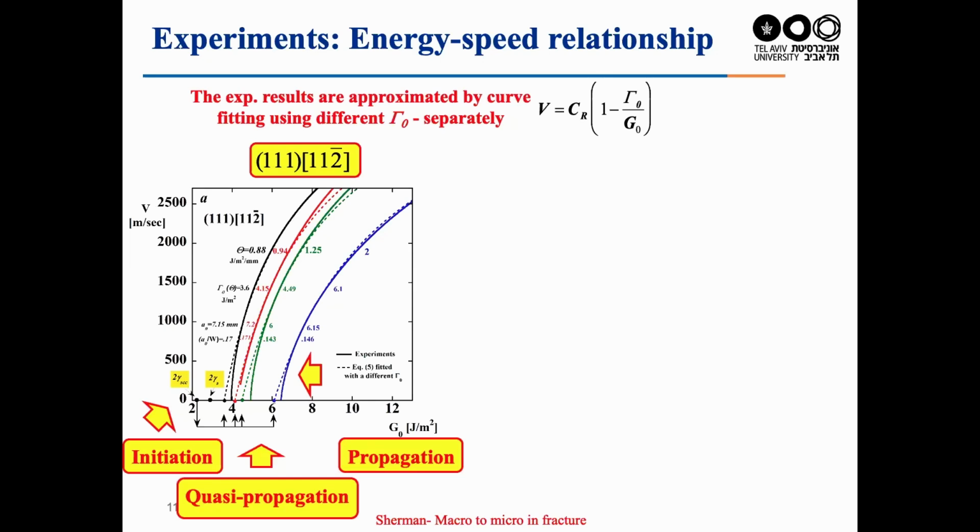So actually, the crack is starting here and propagating for about several microns at very low speed, because the driving force is the temperature, it is the heating temperature. We heat it by 1 degree C per minute, so it may take 2 minutes to reach from here to here. So there is an additional mechanism, quasi-propagation,